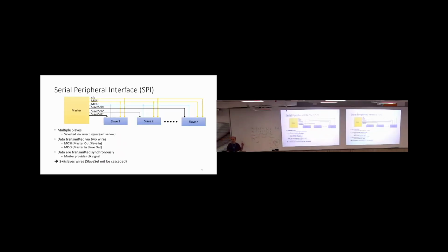Much faster is this SPI. And if I look into nowadays systems or nowadays ASICs that are around, you most of the time also find an SPI interface. It's widely used yet. I would not say it's preferred. So it's kind of, don't know. Yeah, it depends on the specification of your protocol, of your system. It has the benefit, what I can say is it has the benefit that it's faster. So if you want to have faster transmissions with an embedded system, yeah. I mean, if you go for a full-blown CPU, we will anyway go for some parallel protocols and for serial protocols.